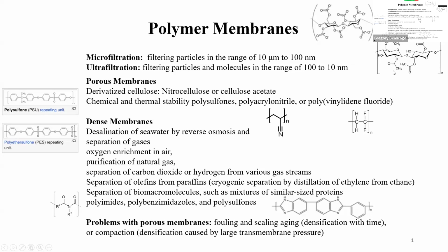Basically the polarity. So they're hydrophilic for water separation, osmosis, hydrophilic, and basically also tough. So basically, they're hydrophilic because when you have a membrane and it's a solid membrane, the porous membranes, you worry about wetting the pores. So you want to have either hydrophilic or hydrophobic if you want to have the pores wet by the thing that's flowing through it.